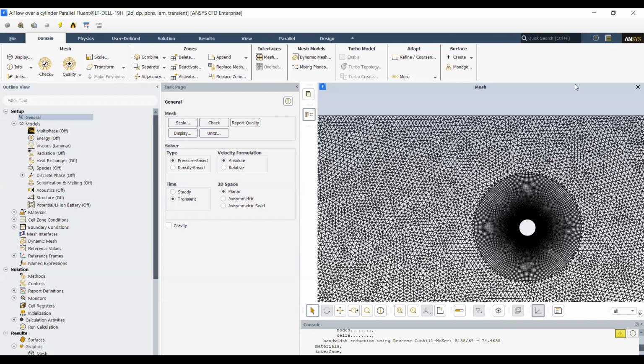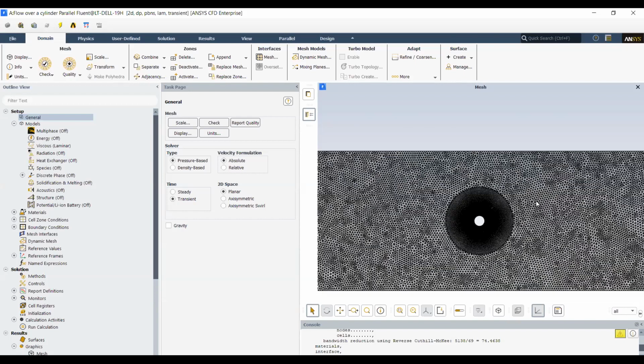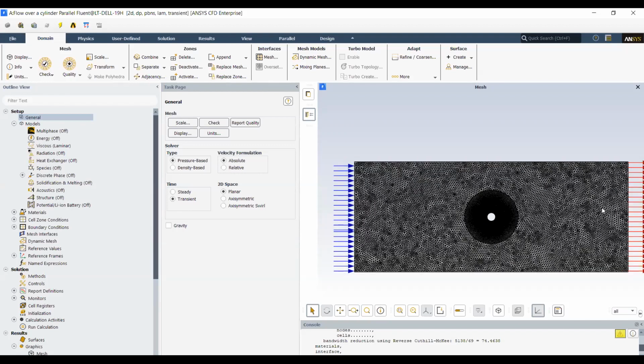Now this CFD setup that I have over here, flow over a cylinder, is not to be taken as a guideline for accuracy. If I were to really look for accuracy, then perhaps I would leave a little more area in the wake region and extend this domain further, because we know that for external flows, capturing the wake region is very important. This is just an example to show you how to set this up. So just use it as a general reference.